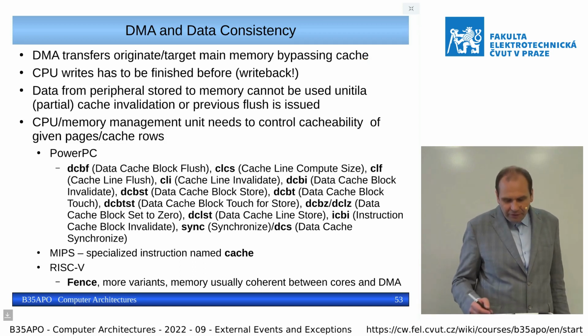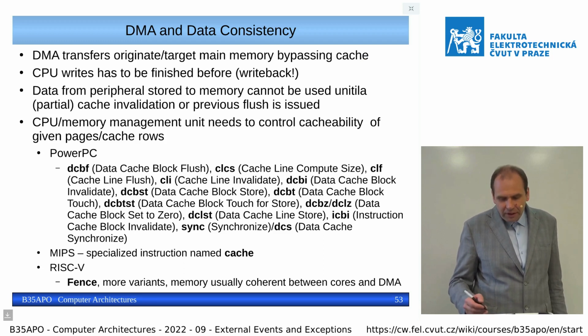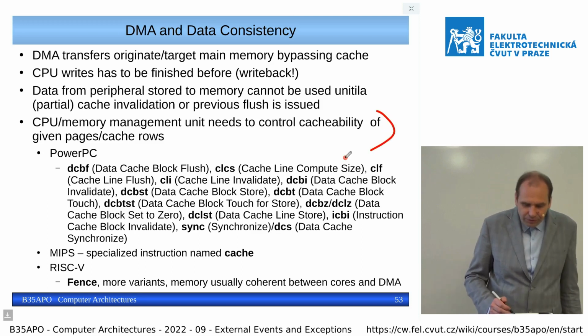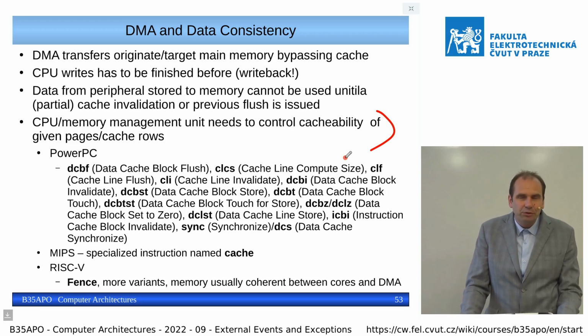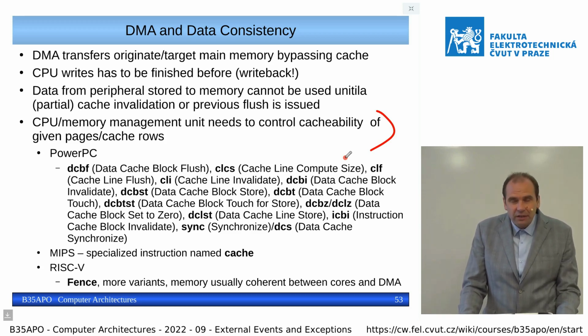On RISC-V and other architectures, you have mechanisms to actually describe the barriers. And for example, for the caches, if you do not have a coherent cache between the peripherals and the CPU core, then it is quite complex. On ARMs, it is usually not coherent.